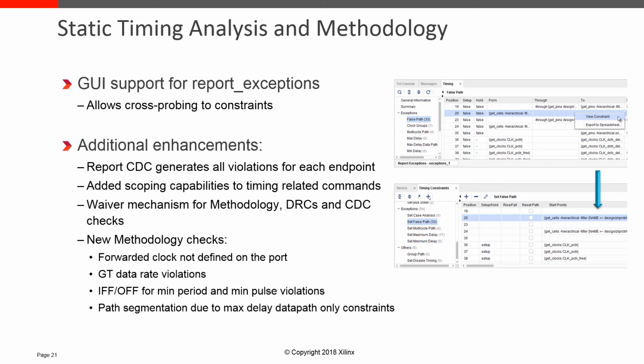The waiver mechanism is now supported in the methodology, DRC, and CDC reports. Four new methodology checks have been added in areas including forwarded clocks, GT data rate, I/O registers, and path segmentation due to max delay datapath only constraint.